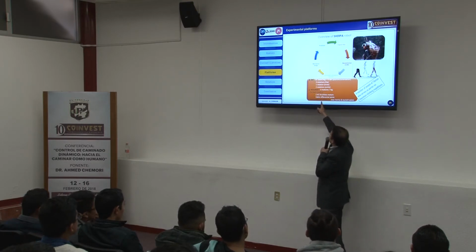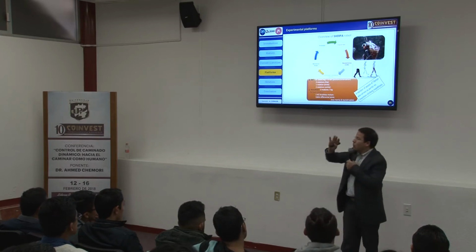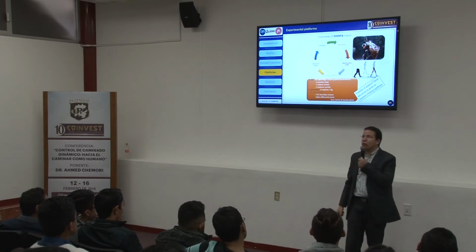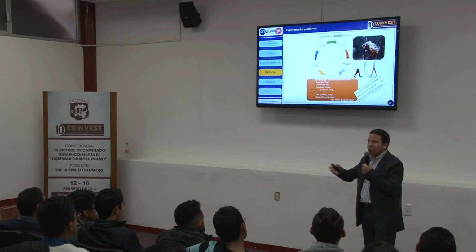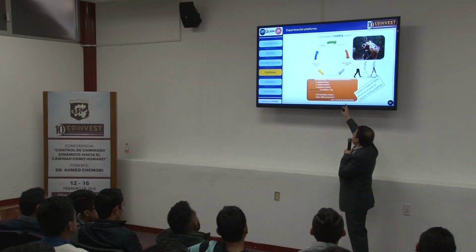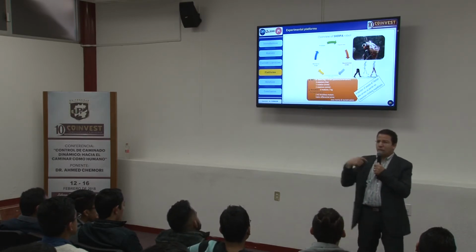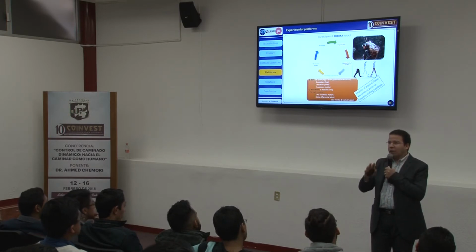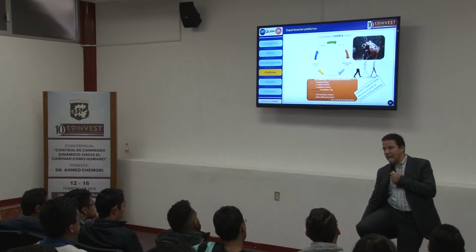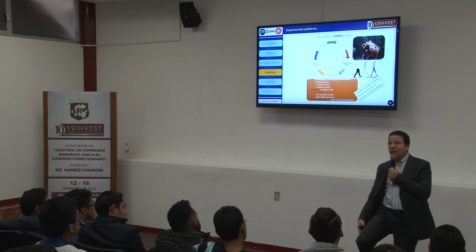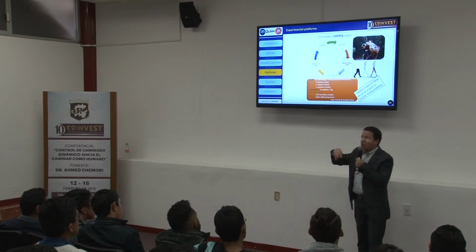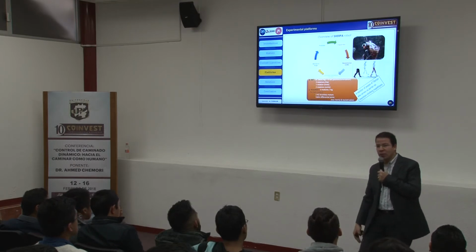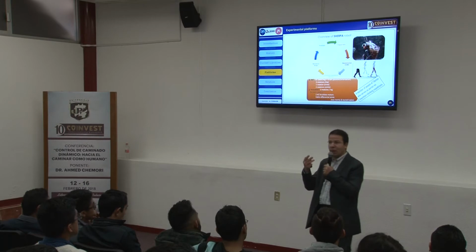And we have this very important feature. This is what we call the transparent actuation. It means that we have low inertia and back drivable. What do we mean by that? It's easy for you to understand. If you see the previous robots, Honda for instance, when you cut all the control inputs, all the currents, the power and so on, and you try to move the leg manually like that, you cannot. It's not possible, because it's not back drivable. So the robot is back drivable if there is no control input, no current coming from the actuators, and if you want to move it, you can. This is what we call back drivable.